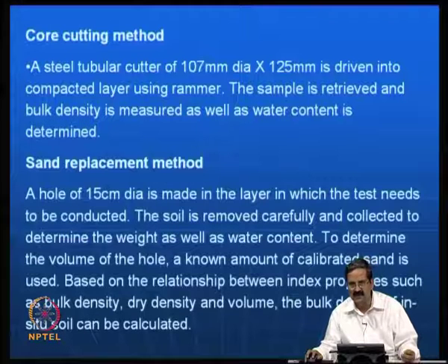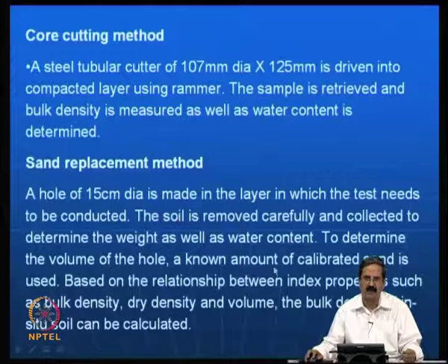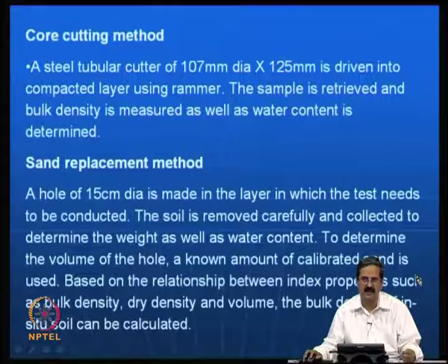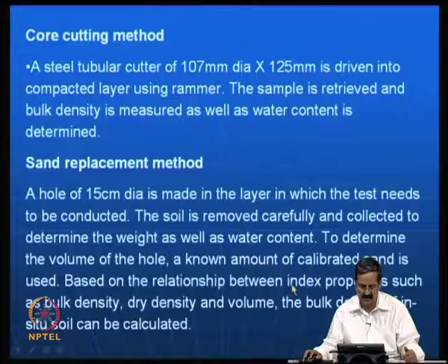The soil is carefully removed and collected to determine the weight of the soil as well as water content. Some amount you can always take to find out the water content. To determine the volume of the hole, a known amount of calibrated sand is used; we should know its sand properties, its density and all that, in a standard volume, and once you know that, one can calculate the density of the in situ soil.